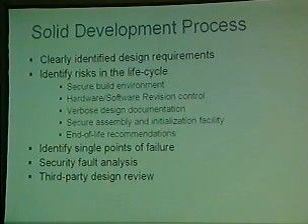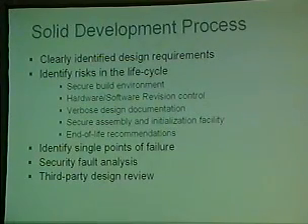Many times as the product is being developed, a change will be made either to the circuitry or documentation or firmware without re-evaluating the security implications of that change, which could lead to a number of problems down the road if you overlook those changes. So you need to have these design requirements solid, and if there is a change, you need to verify that the security still works.